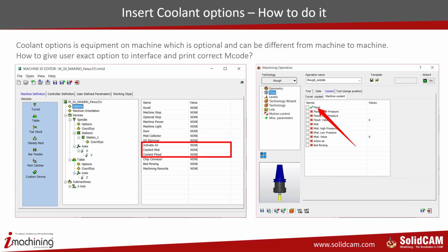When I reach the workshop and go to the front of the machine, I always ask the operator what kind of coolant option this machine has, because if you cannot program that, you will have to insert the manual coolant, or manually turn it on while the part is cutting. So all the time you will need to have an operator in front of the machine. You want to avoid that. You really want to control that. So let me show you how to do it.